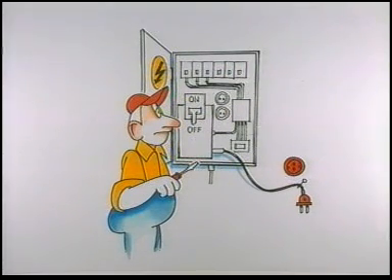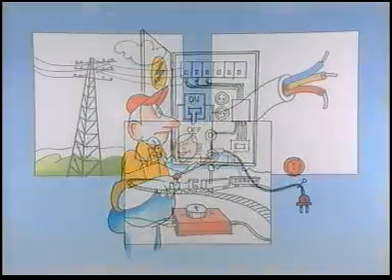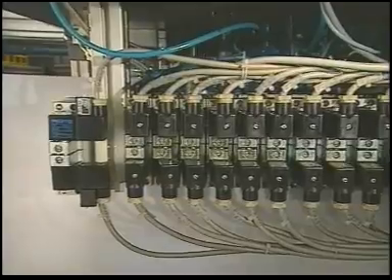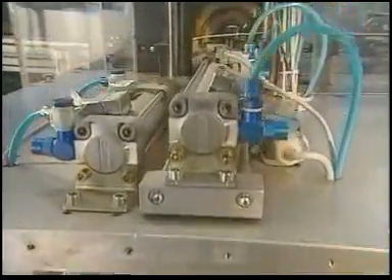Only authorized specialists should make changes to electrical systems, and, of course, only when it has been isolated from the power supply. Other protective measures. High voltage cables are laid in such a way that no contact with them is possible, or so that no voltage can jump across. And current carrying lines are insulated. And finally, low voltages are used wherever possible.